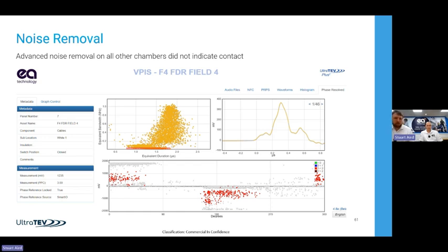So going back to that question in the survey, would you take an outage? This allows us to go from, okay, there's something going on on that panel, to having confidence that it does look like PD, not some other external noise. So that story is getting stronger and stronger all the time, even from handheld equipment. These sorts of techniques have existed on some high-end permanent monitoring systems for a while, but we've built one of the world's first to get this into handheld instruments, and we're about to bring this feature to you for our services.